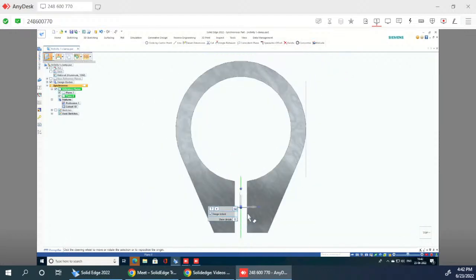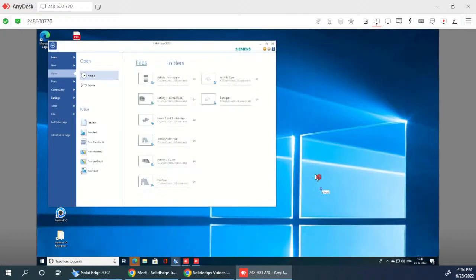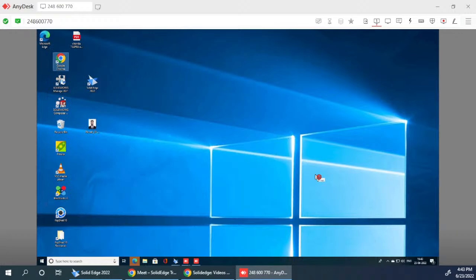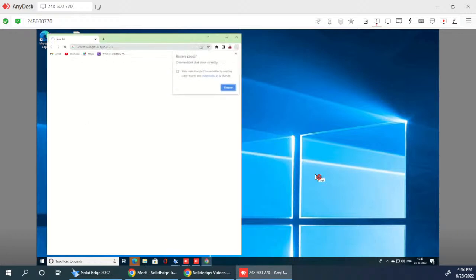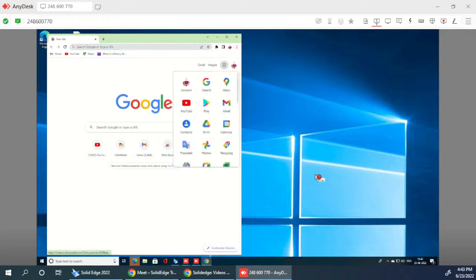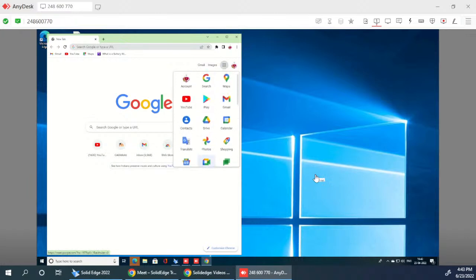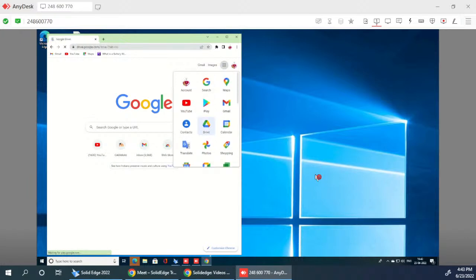Correct? So now from the center, whatever distance he is asking you to offset, that distance you have to offset. Okay. So you need to open the PPT and check what is the distance. Got it? So in the PPT, check the distance and displace it by that value. Then on that plane, create whatever sketch you want to create, and then do extrude cut. Okay. So that should complete your lesson number 3.